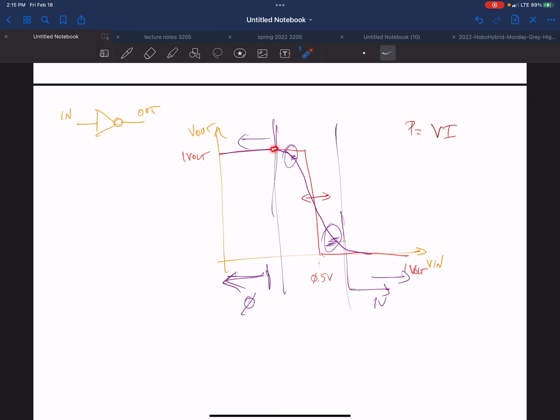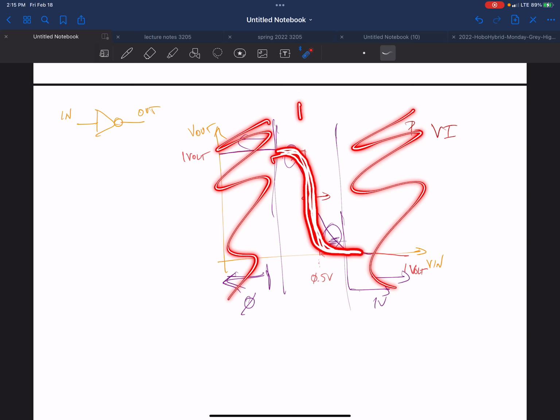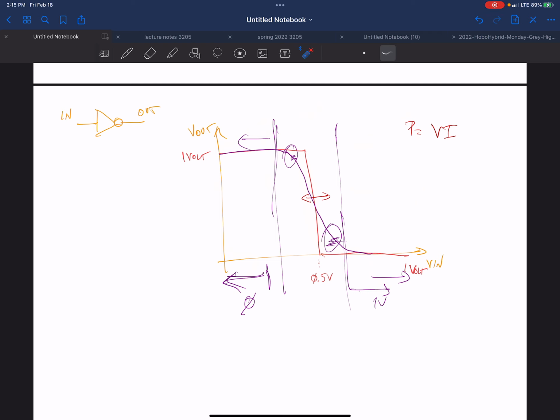You can make this sharper, and we do, for analog design, because there it looks like gain, which is sort of bad in a digital circuit but good for analog circuits. So we'd make these sharp, but at the expense of speed, and you almost would never do that in a CMOS circuit. So in that sense, you don't have control over it.